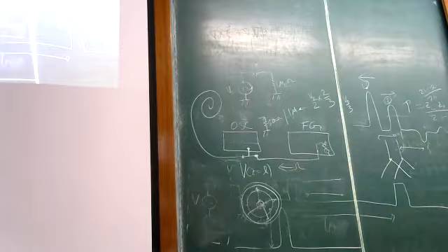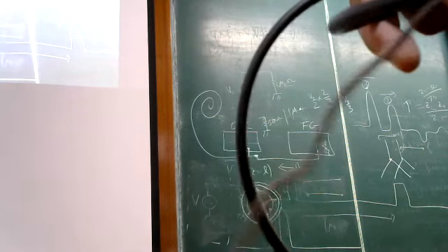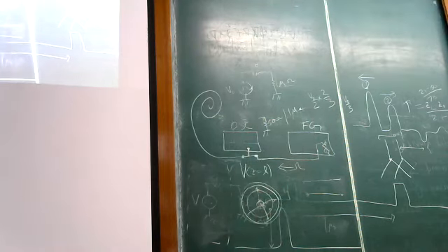The other fat cable, the BNC one, which is here, has much higher diameter. If you compare these two, the black one is much higher diameter. Also, this doesn't have rigid metal inside. It's this braid kind of a thing on the outside, and even the center pin is like a filamentary thing.